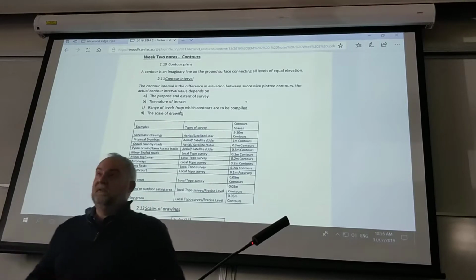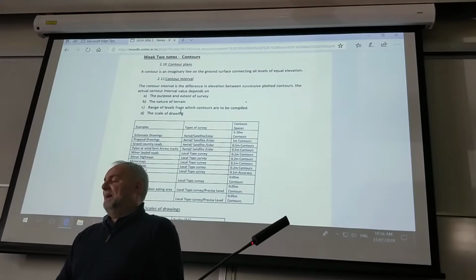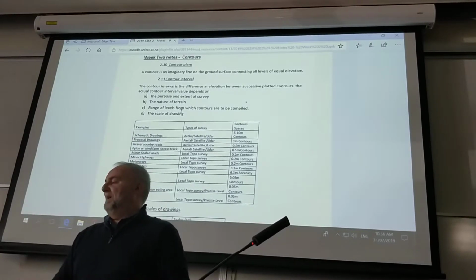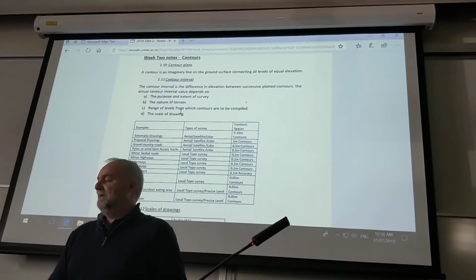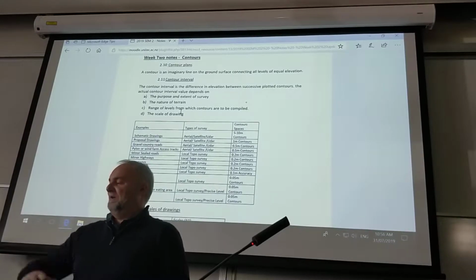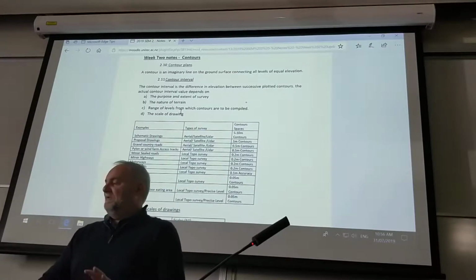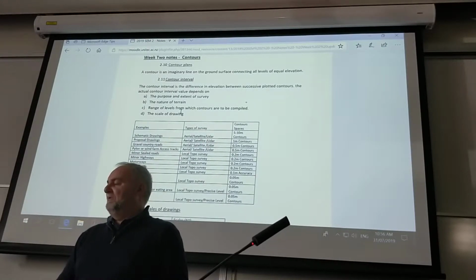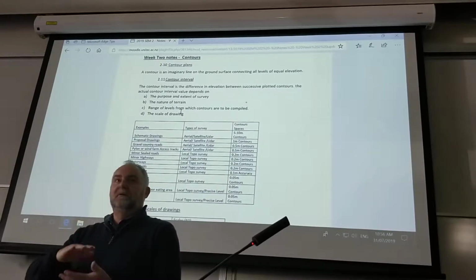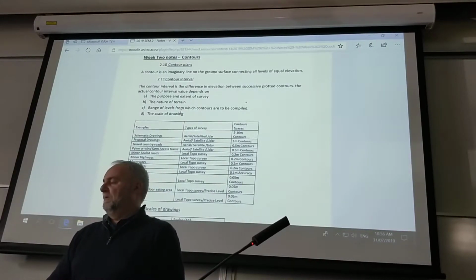For those that don't know anything about motorway design, they have curves on roads, and they have transition curves going into the curves, just so that the cars don't go off the road at 100 kilometres an hour. You're probably driving on the road not even thinking about it, just trying to get the maximum speed out of your car, but all those roads are designed to a speed, and they take into account the inertia, the camber on the road, etc., etc. So designs for motorways, highways, sealed roads, you're going right down to a lot smaller contour interval.